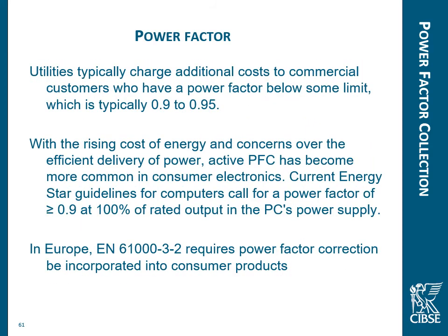So with power factors, anything over 0.95 is probably not worth getting overly concerned about. But as we start to get below 0.95, 0.9 or even 0.8, then we ought to be concerned about it and try and take steps to correct that.